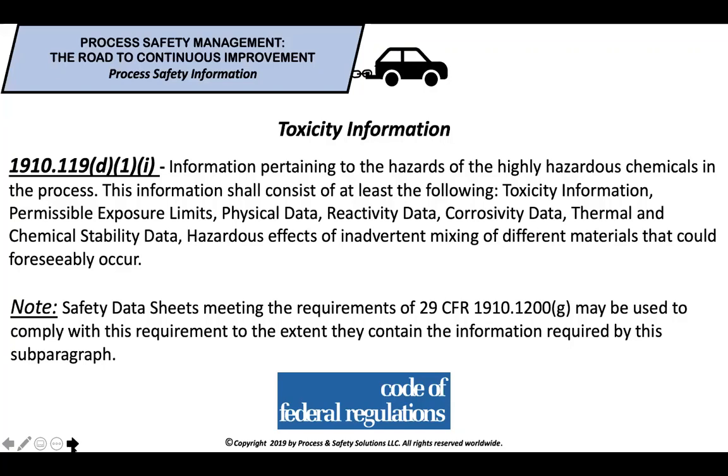Most people will fulfill this portion of the requirement through safety data sheets, and most of your safety data sheets will contain this information. Some of the information that they will not contain in a lot of cases is the inadvertent mixing of the different materials. There's no way they could foreseeably see every possible scenario of mixing that chemical with something else. So you as a facility must look at that specifically to determine if there are any hazardous effects of inadvertent mixing with the chemicals that you actually have in your process.